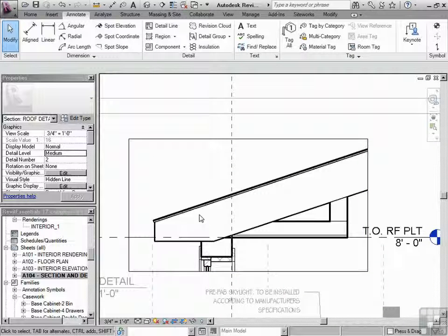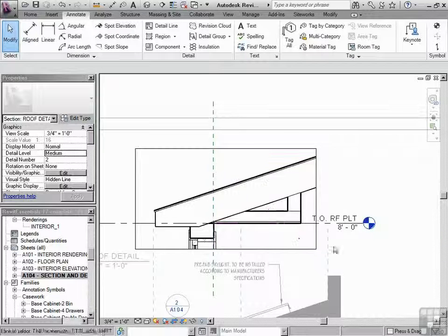Really, that's filled regions, and you want to use that as much as you can as opposed to just drawing and trimming the old CAD way. This tends to be a little bit nicer in that you can draw something and have it hatched all at the same time. Now, what about some other things in here? We might want to draw some hidden lines, some studs and all that. So those are things that we'll need to look at in other videos.